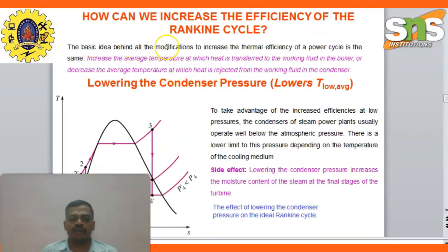The basic idea behind the modifications to increase the thermal efficiency of the power cycle is the same: increase the average temperature at which heat is transferred to the working fluid in the boiler, or decrease the average temperature at which heat is rejected from the working fluid in the condenser. Lowering the condenser pressure takes advantage of the increase in efficiency at low pressures. The condensers of a steam power plant usually operate well below atmospheric pressure. There is a lower limit to this pressure depending on the temperature of the cooling medium.